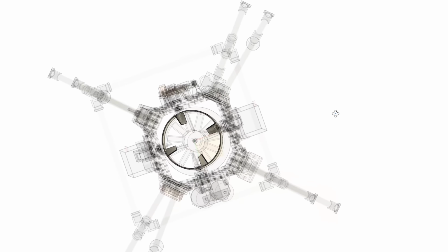So I added more stators to the fan. A stator is a static fin that goes in the airflow, at least in this case. And the reason I added them is because of the roll torque from this fan. We don't have two counter-rotating fans, we just have one. So there's a lot of torque from that motor trying to spin this fan with its air resistance and all the things that go on with it. So I added 4 extra stators that sort of counteract that roll.